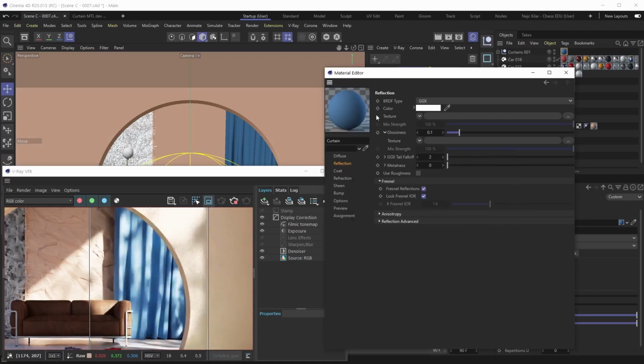And so that's a pretty important touch of realism you can add to your materials. And as you can see, even fabric materials that have a really low glossiness value exhibit a visual change when you turn reflections on. They just look a lot softer, a lot more realistic. Now, again, if you have a fabric glossiness texture, feel free to plug it into the glossiness texture slot here.